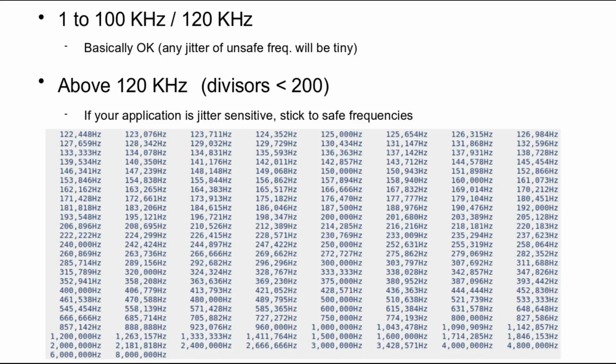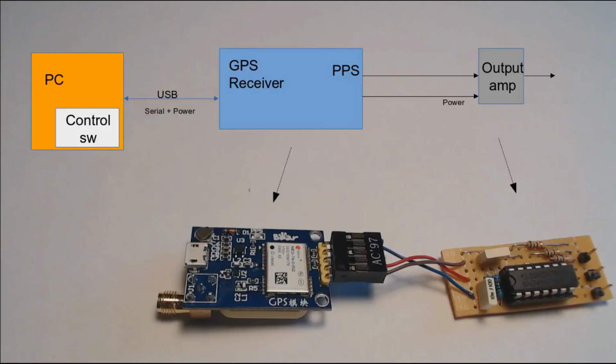I'm thinking to add a safe frequency only option into the little utility I wrote to replace uCenter, but I'll cover that in a follow-on video. Because of the way the output signal is assembled from bits of different frequencies, I would not use this method as a frequency generator for producing high-quality signals for general use at arbitrary frequencies. If you need that, you better look for a decent function generator instead.